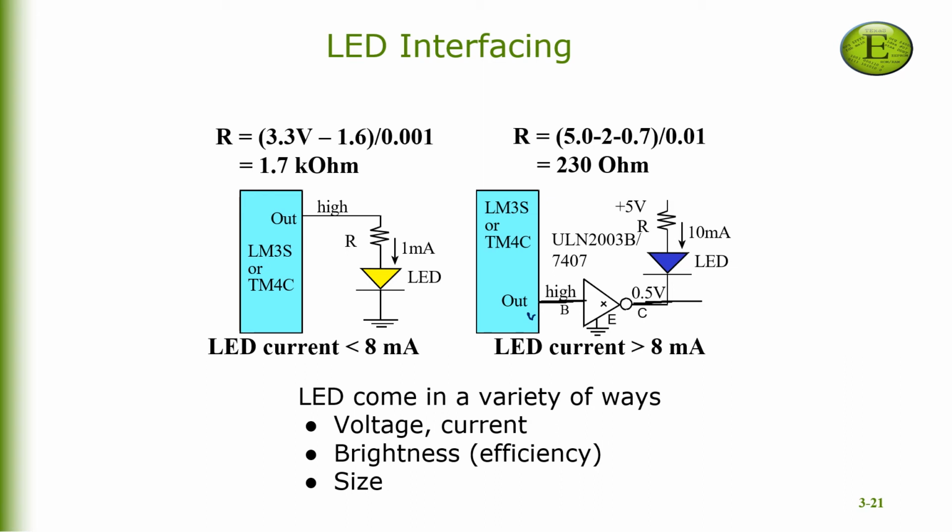The 7407 IC produces a low output when the input is high, and it produces a high impedance state, that is Z, when the input is low. So when the input is low, there can be no current passing through the LED. But if the input is high, then the output is low, meaning that some current can pass through the LED.